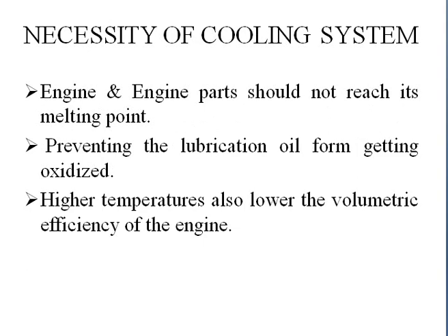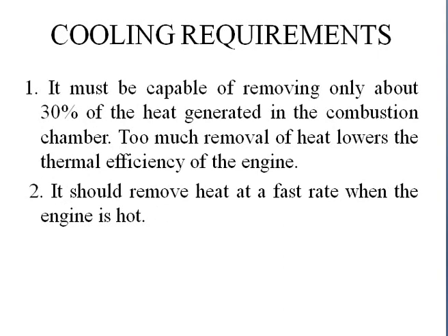The necessity of cooling system is that the engine and engine parts should not reach their melting point. Generally the energy which is released is so high that it will melt the parts present in the engine. Because of the cooling system, as the temperature is under control, these parts work properly. Next is preventing the lubrication oil from getting oxidized. It means if the temperature is too high, the lubricating oil will get oxidized, and the rupture of parts will take place. Next, higher temperatures will decrease the efficiency of the engine. Because of these reasons, we have a cooling system.